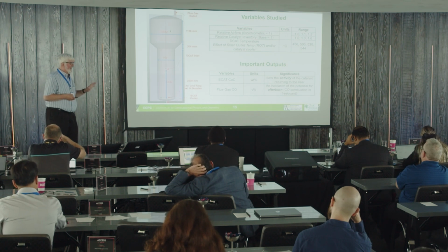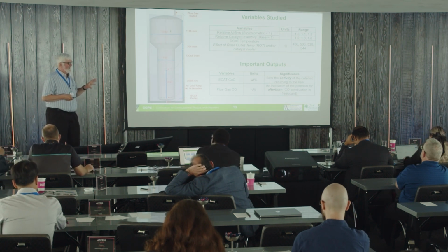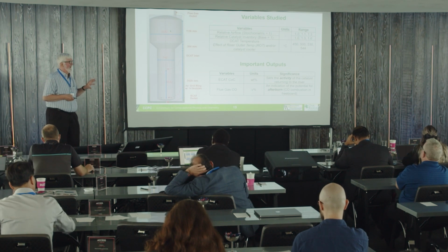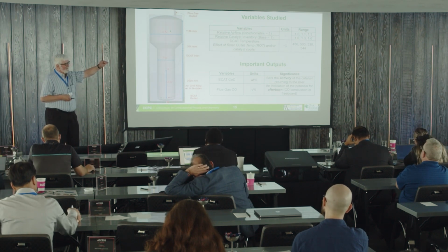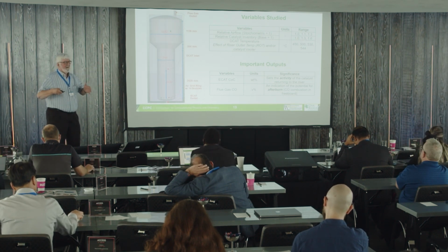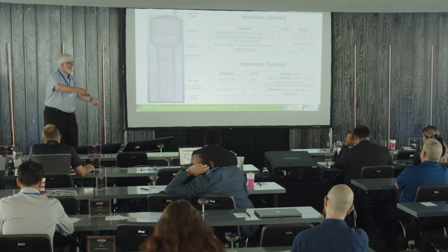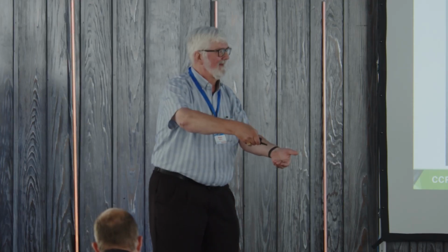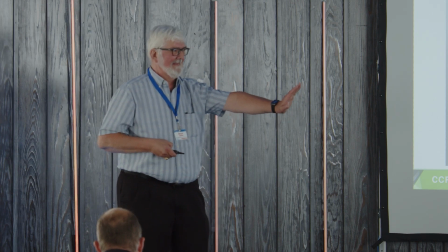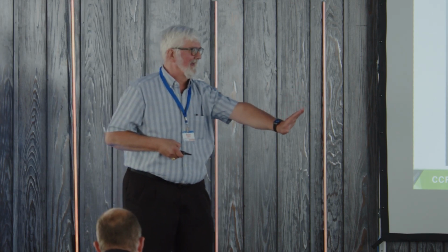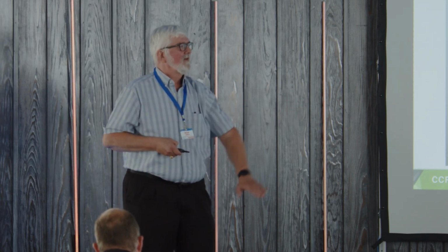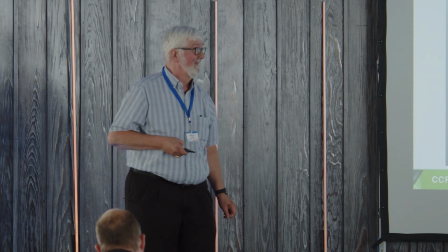I actually toured a regenerator, I can't tell you where it was, a big one, running 140,000 barrels a day. I walked in between the stripper and the regenerator, and they had like a 10-inch steam pipe blowing live steam on top of the regenerator, and I got within, I don't know, 10 feet of it. I said, I'm out of here. I can't do that. Why are you doing that? To cool the regenerator head with live steam, because the thing was constantly in afterburn.